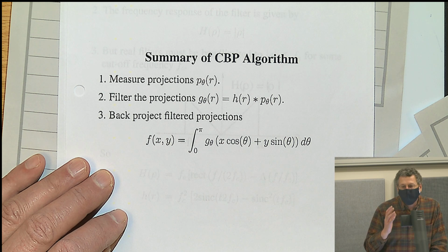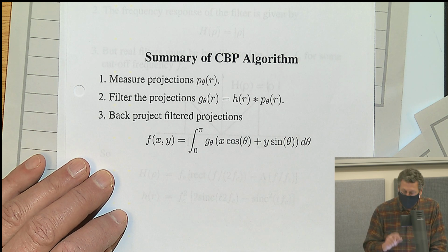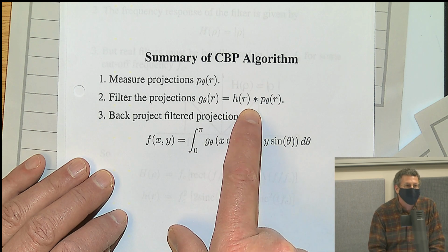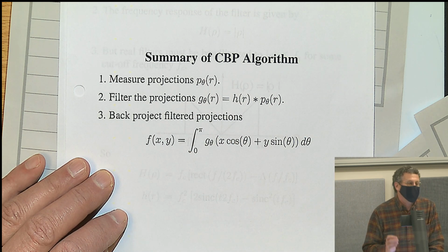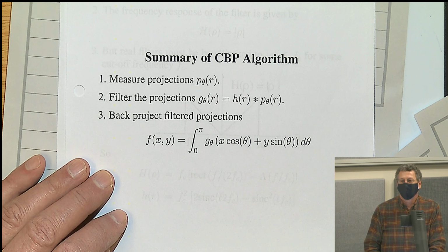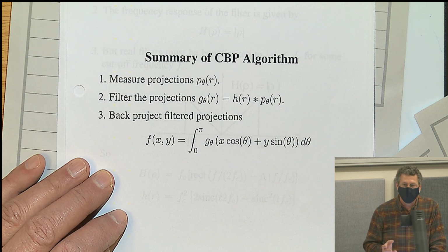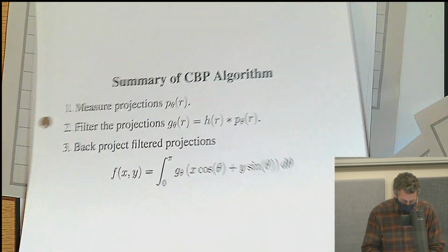But it doesn't do the inverse. What's interesting is that for the Radon transform, if you filter the projections, then it does become the inverse, because it reconstructs the image from its projections. That only works if you have an infinite number of projections and the signal's band limited. Okay, but it does work in that case. So that's kind of interesting.